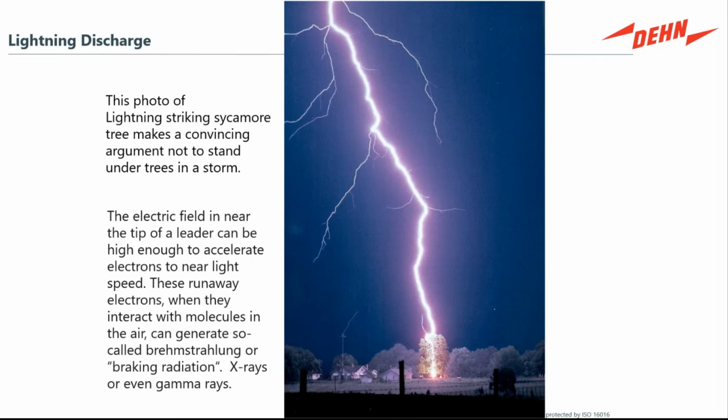I like to use this photo as an introduction on lightning because there's really a lot going on, but it gives you a really good picture of who's who in the zoo of lightning. And what I really like to point out is the antenna off to the left is not the main return channel, the main stroke attachment for all that lightning charge. It's a sub-strike, a step leader off to the side that didn't form the main channel,